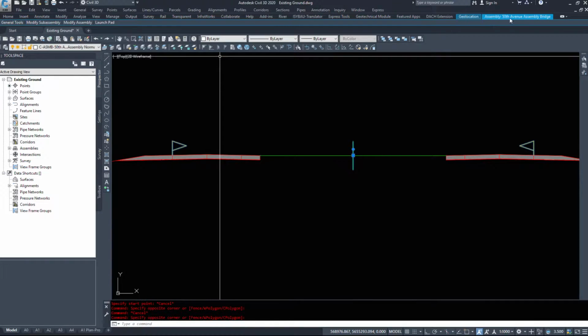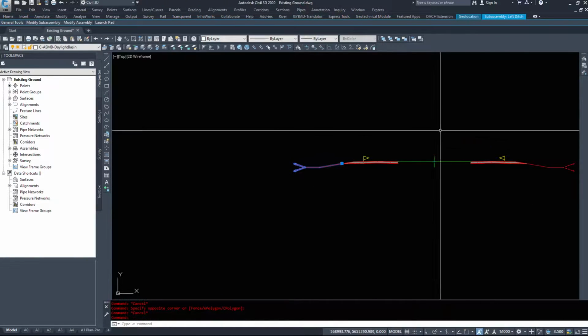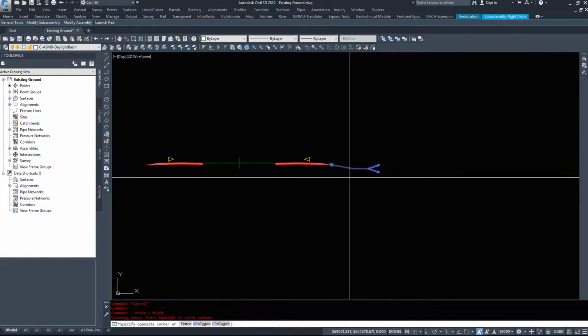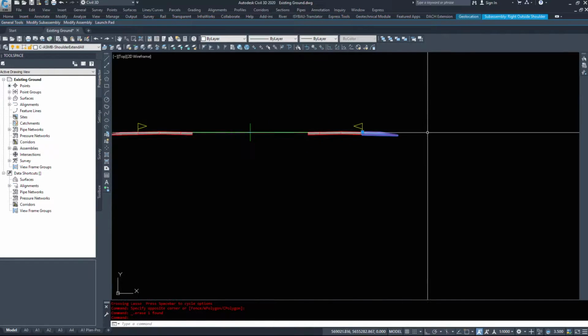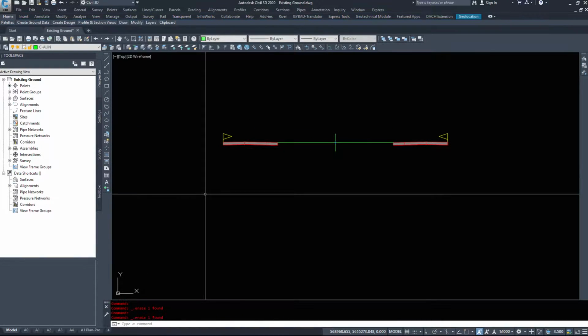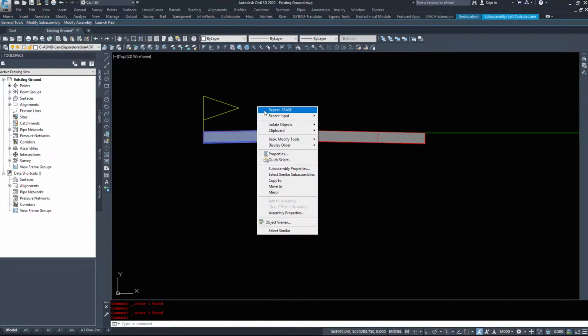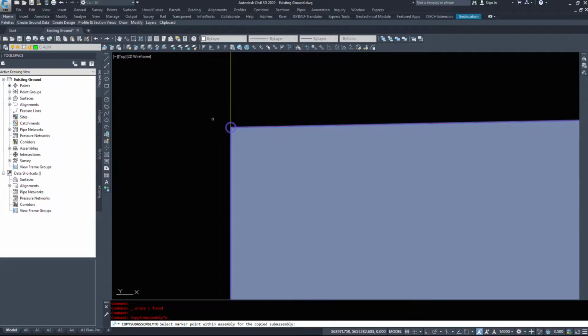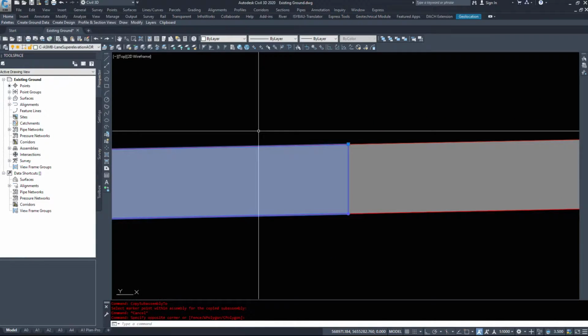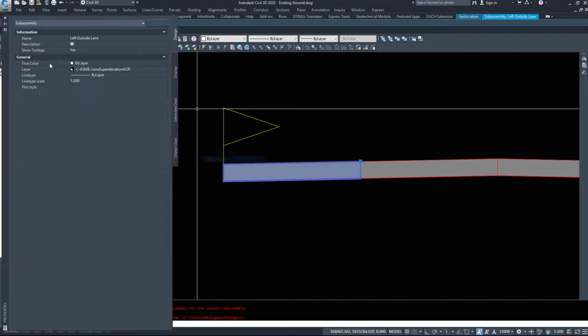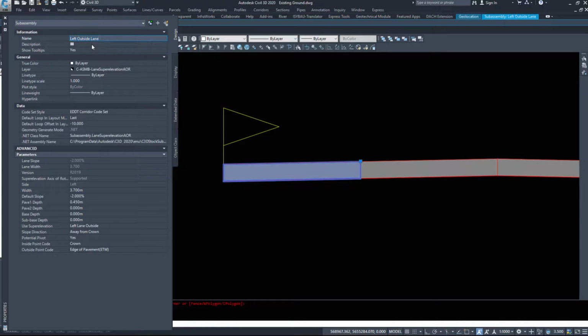So now I've got this named 50th Avenue Assembly Bridge. I've deleted the median. I will delete the ditches on both sides, and I'm also going to delete this shoulder because we don't taper shoulder on a bridge here. I'm going to right click, copy this road piece to there, go to properties, rename it left outside shoulder, and make this 3 meters wide.